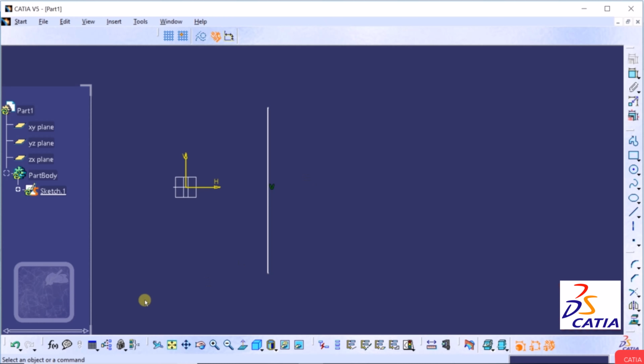So now what I do, I undo this and now I try to pick this endpoint. Take the mouse onto this endpoint and try to drag it. We can see we can drag this point. I can reduce the length of this line. I can also increase it with this mouse. I can also make some changes into the angle. Similarly, when I take the mouse onto this endpoint, just hold down the left click and drag the mouse. We can see we can drag this line from the bottom point also. So it means this line is right now not fixed. This line is not constrained.